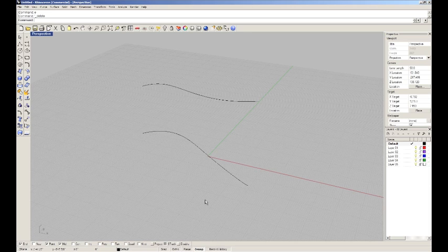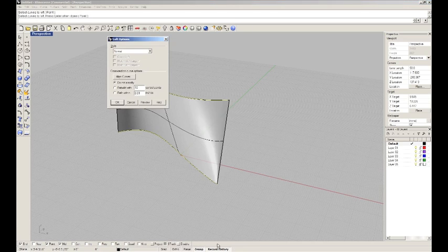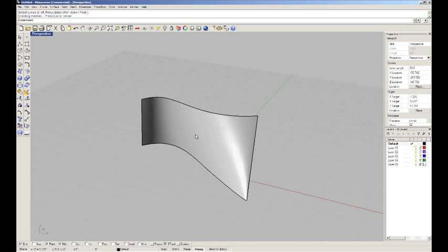And what it does, if I turn this on, so if I just click on it and make it bold, and loft the surface again. So I'm selecting the same two lines and I'm lofting them, but Record History is on, it's bolded. I'm going to loft it the same way. And you can see that I have it set in here to not always record. So what that means is that the Record History option will stay on for one command and then automatically turn itself off. I definitely recommend this as the setting. If you accidentally have Always Record History on, you'll just run into major problems. So anyway, we have lofted this surface again using the Record History option.